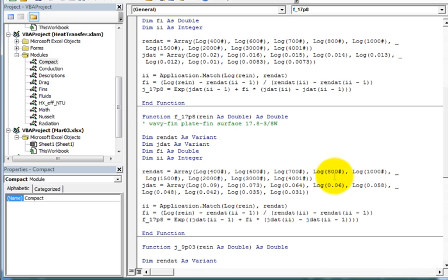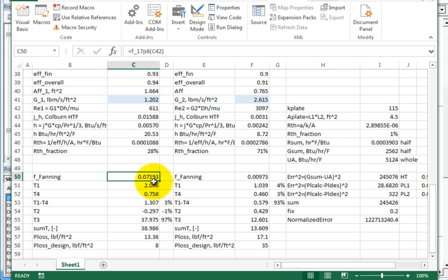And this data, I didn't read off of it. That data I got out of a different source. I found it for both the friction factor and the Colburn heat transfer factor for both of those surfaces. So those get updated, and then we could take a look at our pressure losses. Now you can see what happened to the pressure loss. It went up. And what about the pressure loss over here? Down quite a bit. So you change your dimensions, that's changing the length of the passages, and then it changes.